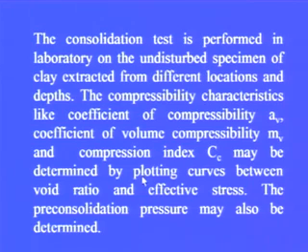The consolidation test is performed in the laboratory on undisturbed specimens of clay extracted from different locations and depths. The compressibility characteristics like coefficient of compressibility a_v, coefficient of volume compressibility m_v, and compression index C_c may be obtained by plotting curves between void ratio and effective stress.